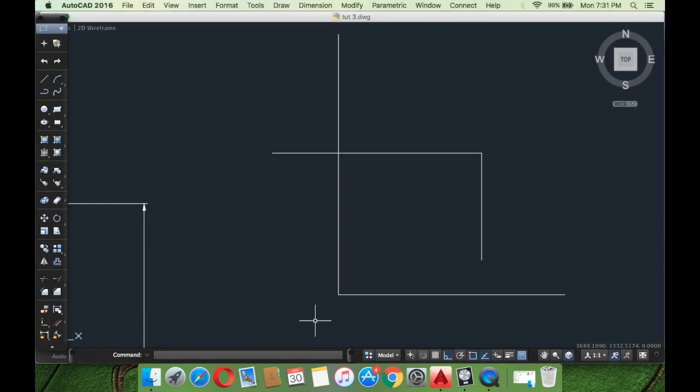Over here, the lengthen tool is this one, or the extend. You can use it. It's very simple. So you select it from over there, or you can type extend over here. In this case, you simply follow the method that I taught you for trim. You select the boundary there, we press enter, and then you select the object that you want to extend. It's as simple as that.